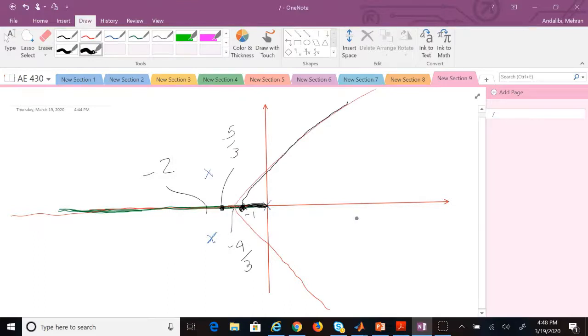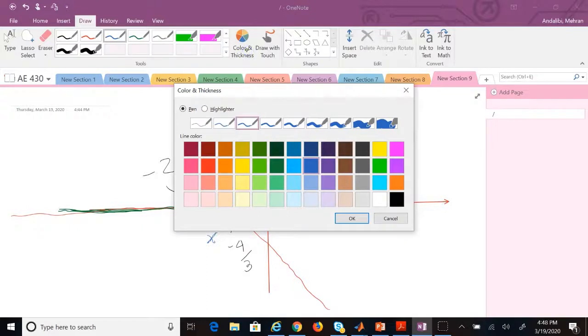So the root locus, one branch is like that. Then the other branch goes from this point, let me use a different color. It exits at negative 63 degrees, comes and hits here, and then goes to infinity. So one of them should go like this.